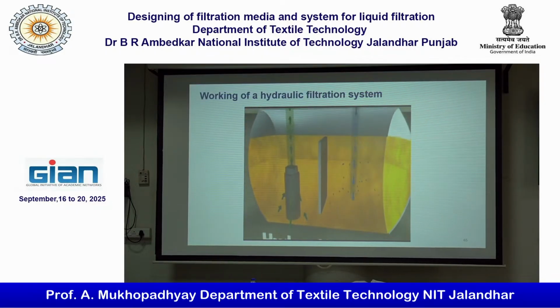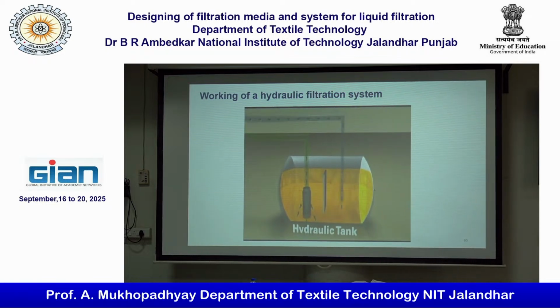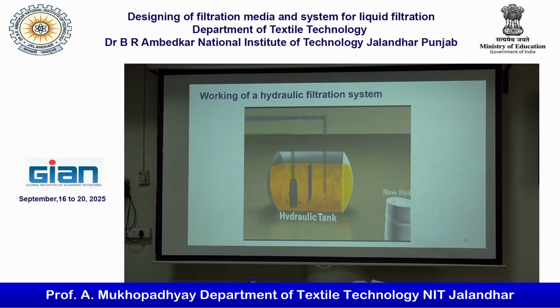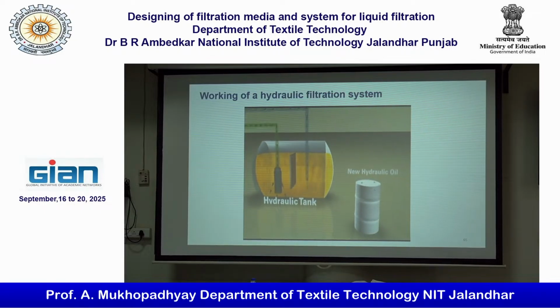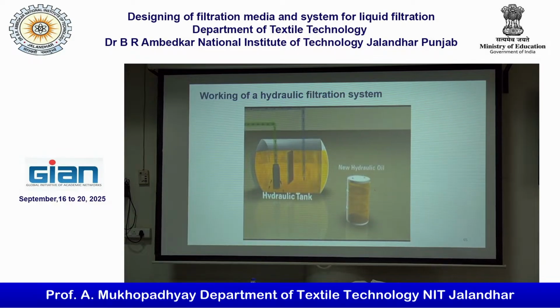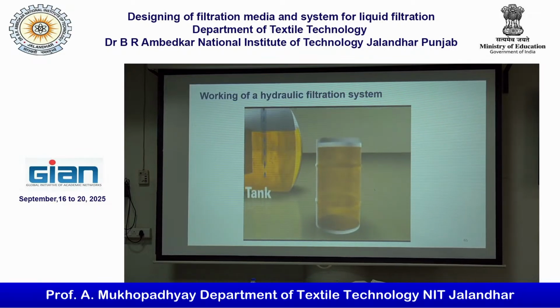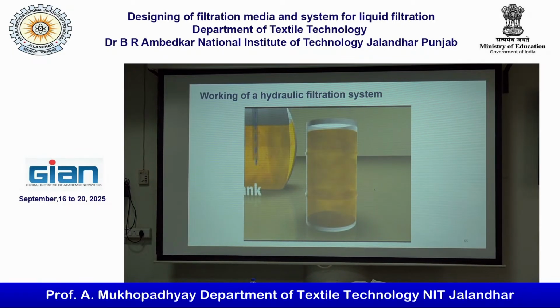It's here that most of the contaminant finds its way into the oil. First, it's important to note that new hydraulic oil is not pure. At an approximate ISO cleanliness level of 21/19, it is significantly higher, that is less clean, than OEM standards.